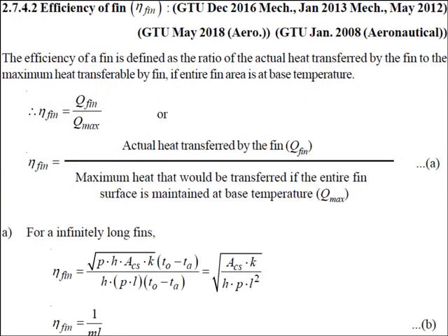Now the second important term which we have to discuss is fin efficiency. Fin efficiency is defined as the ratio of actual heat transfer by the fin to the maximum heat that would be transferred if the entire fin surface is maintained at base temperature. So you can say it is the ratio of heat transfer with fin to the maximum heat transfer.